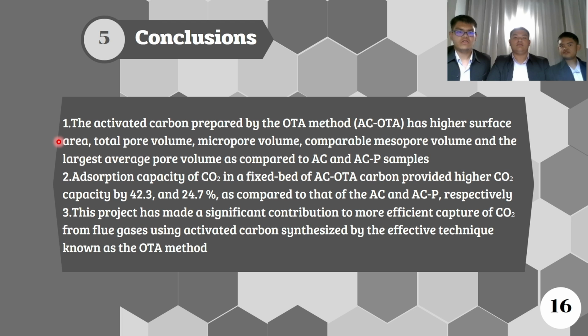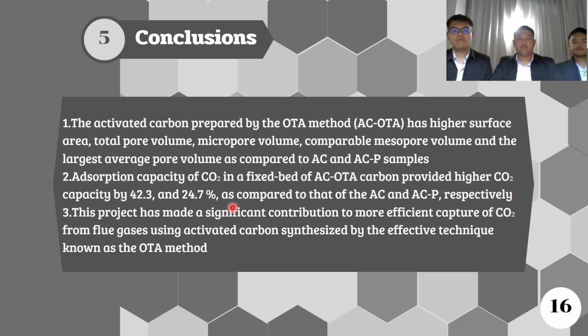Next is our conclusion. 1. The activated carbon prepared by the OTA method has higher surface area, total pore volume, micropore volume, comparable mesopore volume, and the largest average pore volume as compared to AC and ACP samples. 2. Adsorption capacity of carbon dioxide in a fixed bed of AC OTA carbon provides higher CO₂ capacity by 42.3 and 24.7% as compared to that of the AC and ACP respectively.